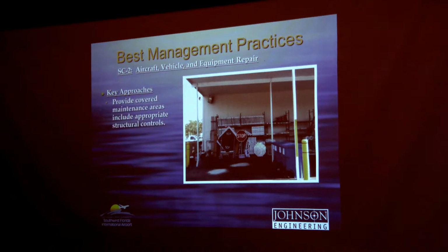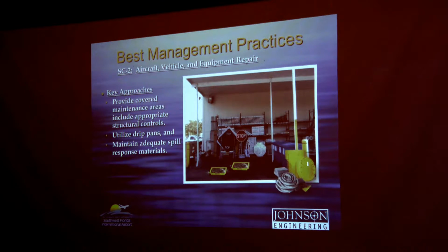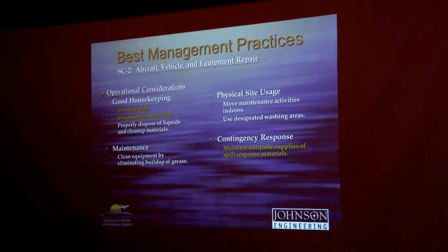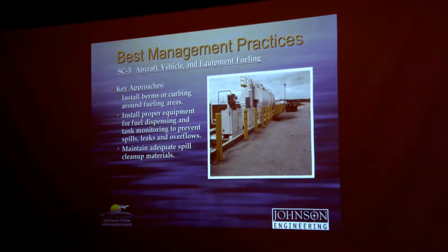SC2 is aircraft, vehicle, and equipment repair. Key approaches here include providing covered maintenance areas and including appropriate structural controls, utilizing drip pans, and maintaining adequate supplies of spill response materials. Additional operational considerations include properly disposing of the liquids and cleanup materials that you use, cleaning equipment regularly and eliminating the buildup of grease so that that doesn't fall off in an uncontrolled area, moving maintenance activities indoors or under covers where you can, and using designated wash areas.